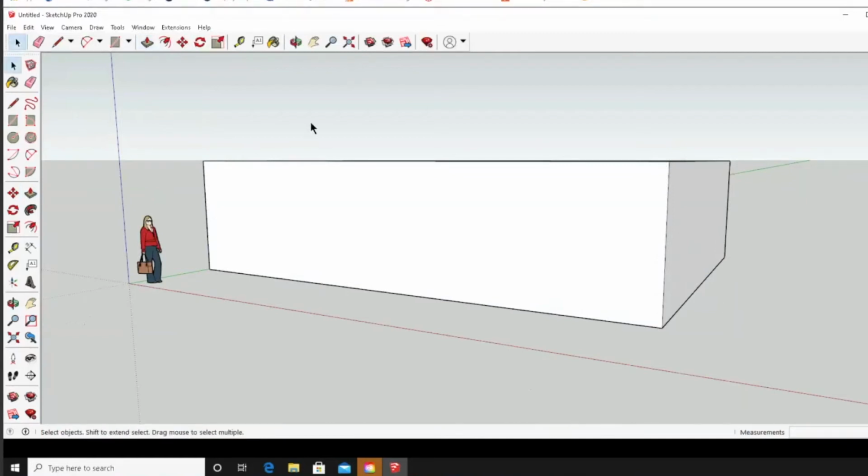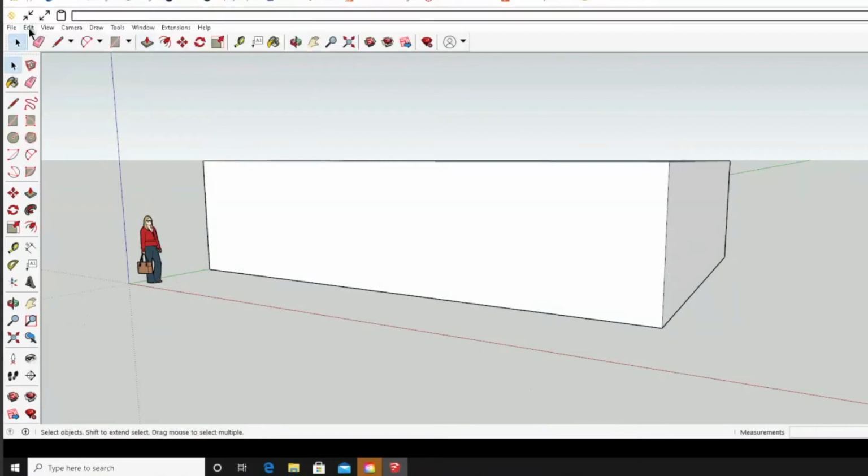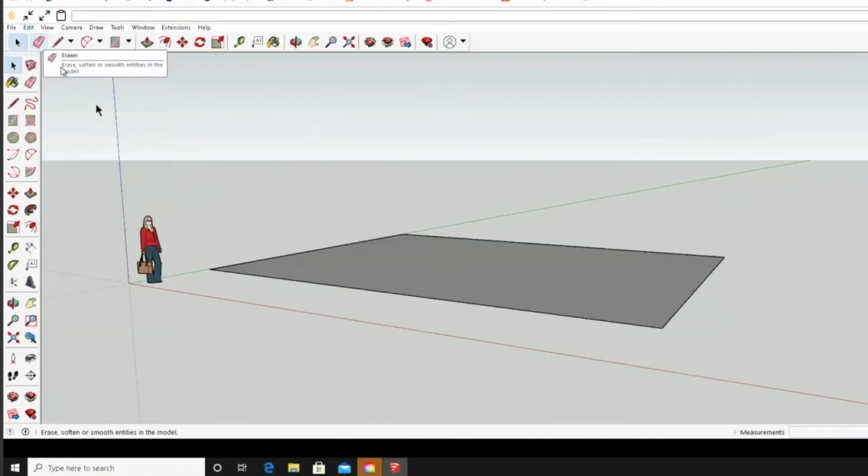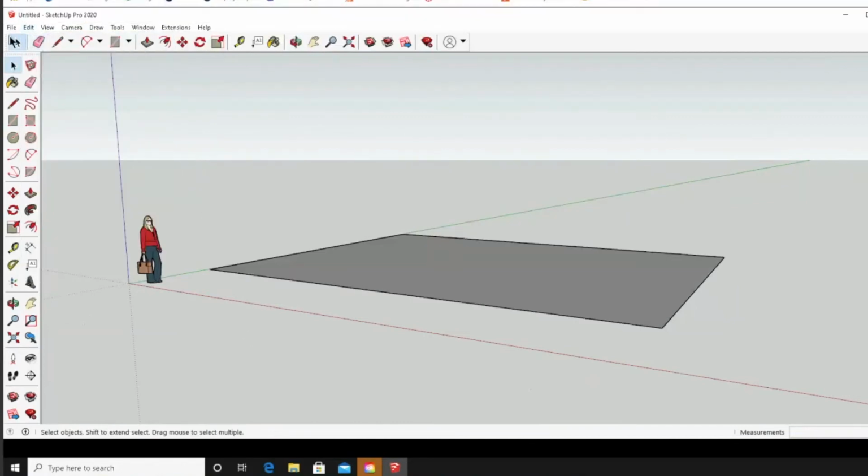So in Chief Architect, Oh, Cory, can you show me again how did you put the measurements for that? Sure. So I'm going to edit and I'm going to undo the push and pull. Okay. All right, so select tool. Okay. So I'm going to select the push pull. Okay. And then I hover by the rectangle and I'm selecting the surface that I want to pull up. And you can see that it's selected when those dots appear.